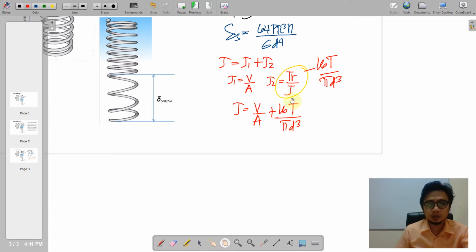So in short, we need to express this in terms of force. And what is that? If we are going to have this illustration here, say this is the wire diameter, where P is concentrated along that axis. The distance involved here from the center is the mean radius R. Therefore, our torque is the product of the actual load P times the mean radius.